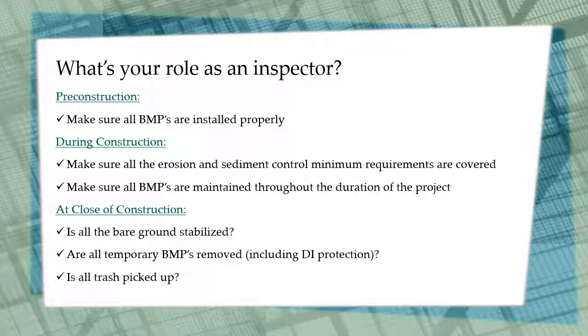So what's your role as an inspector throughout the life of a project? Well, before a contractor breaks ground, make sure that all the BMPs are installed properly and where they should be. During construction, make sure that all the erosion and sediment control minimum requirements are covered, such as stabilizing the construction entrance, having a waste container, having a concrete washout.